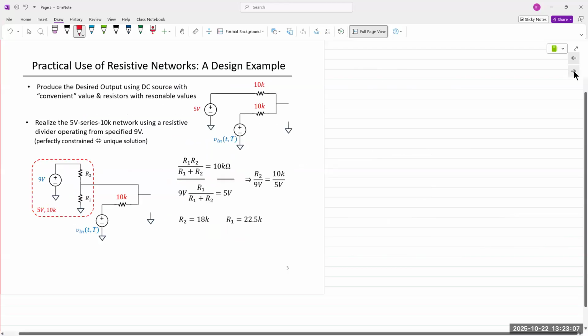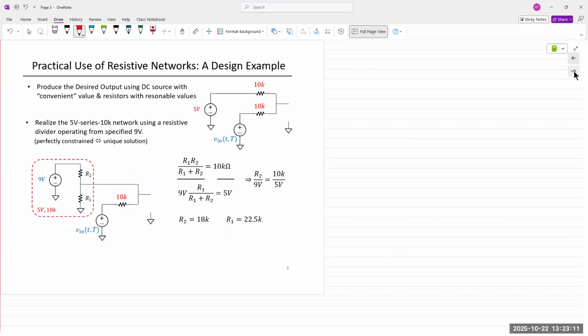Since we're shifting it up, we're going to take our waveform and add a 5-volt DC value to it. That would shift our entire waveform up. Anytime you have an AC signal and you add it to a DC source, it's simply going to add in there, meaning the reference level is going to shift up or down depending on the value of our DC source.